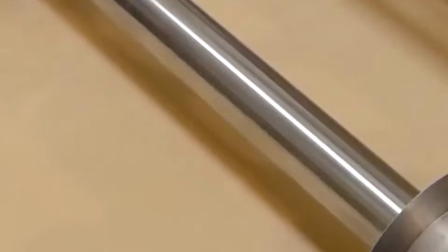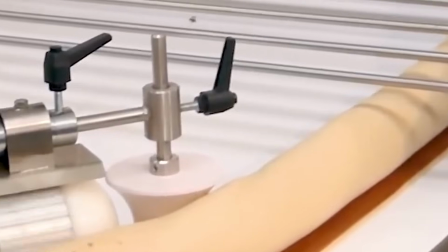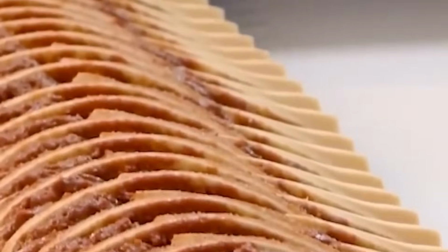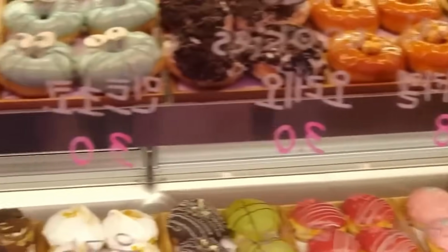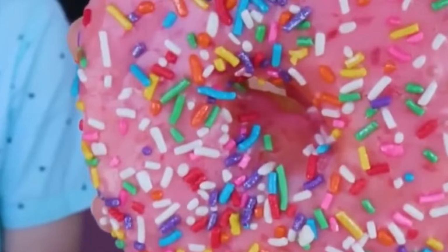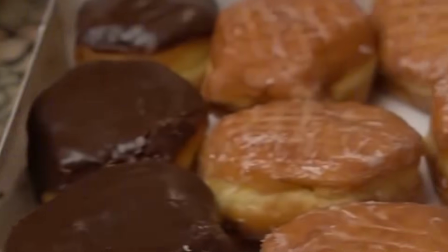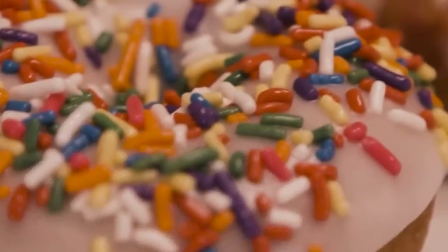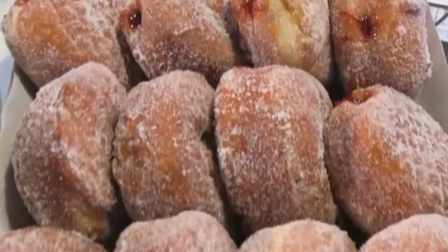Staging silos and ingredient feeders are equipped with load cells to precisely meter dry ingredients. Liquid ingredients are stored in jacketed stainless steel tanks with inline agitators to prevent settling or stratification. The dry and liquid ingredient streams merge at the mixer's inlet via butterfly valves controlled by digital weigh scales. The dosing accuracy ensures batch-to-batch uniformity, critical for dough performance during proofing and frying.